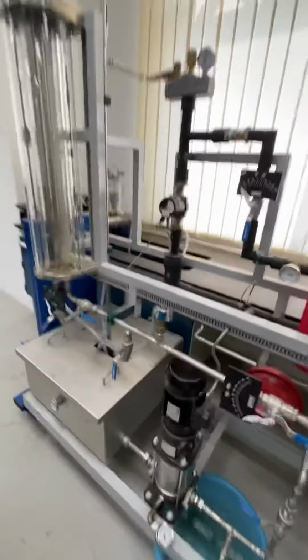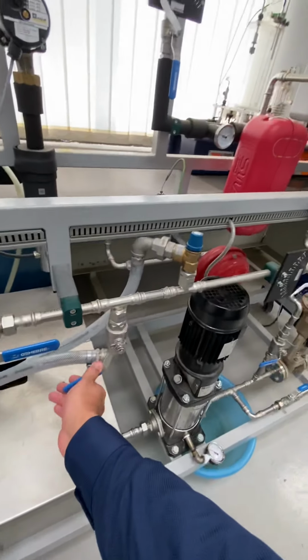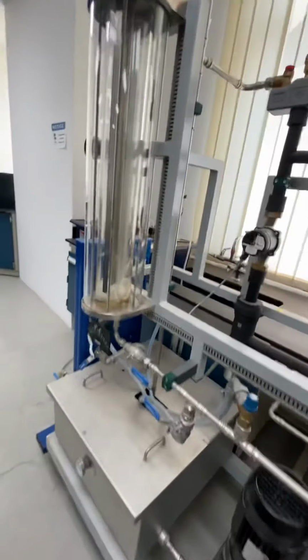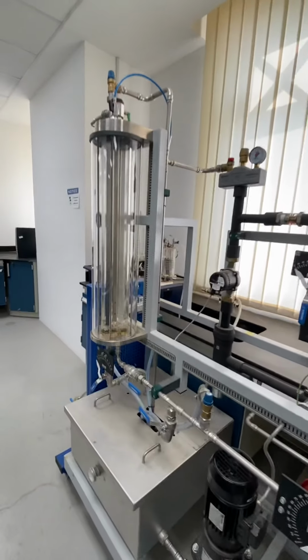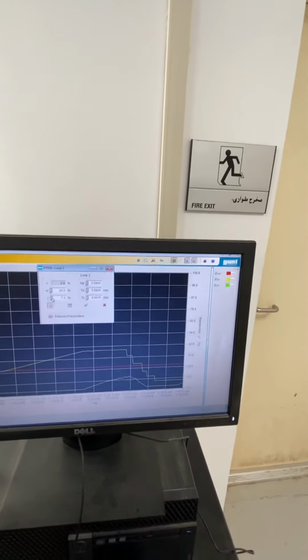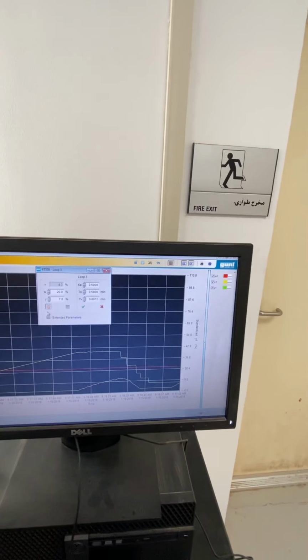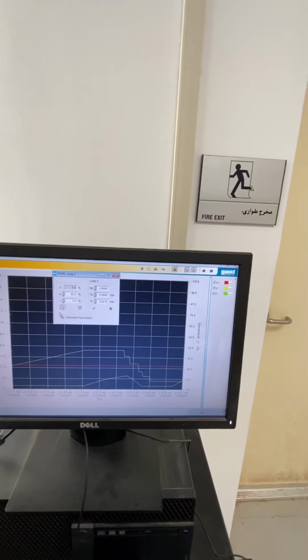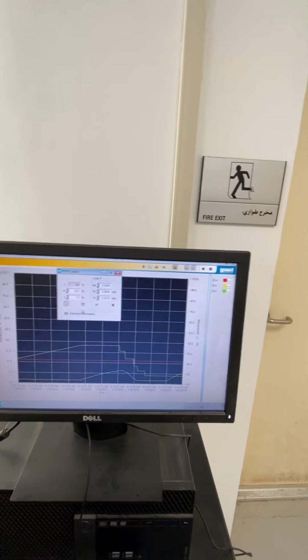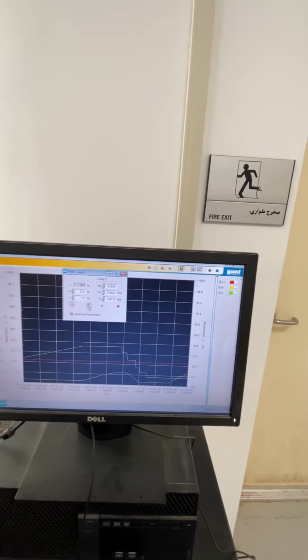And we close the valve, V11. So you can see right now that the flow rate is actually going to V2. And that's why you'll see that the level will start to increase. I'm doing this manually, so let's hold on and wait for the process value to become very close to the set point, and then we can switch to the automatic mode.